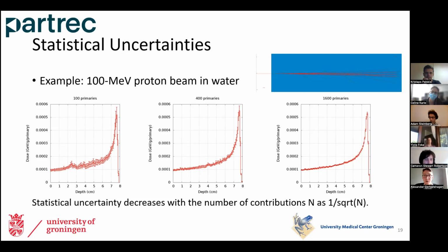But of course, it would be nonsense if you are just trying out the simulation and building it up to let it each time run 2.5 days. So in the beginning, when you are setting it up, you probably want large statistical uncertainties for the sake of better computational time. And then once you are certain that what you are calculating makes sense, then you can reduce them by letting the final simulation run longer. All right, thank you. You're welcome.